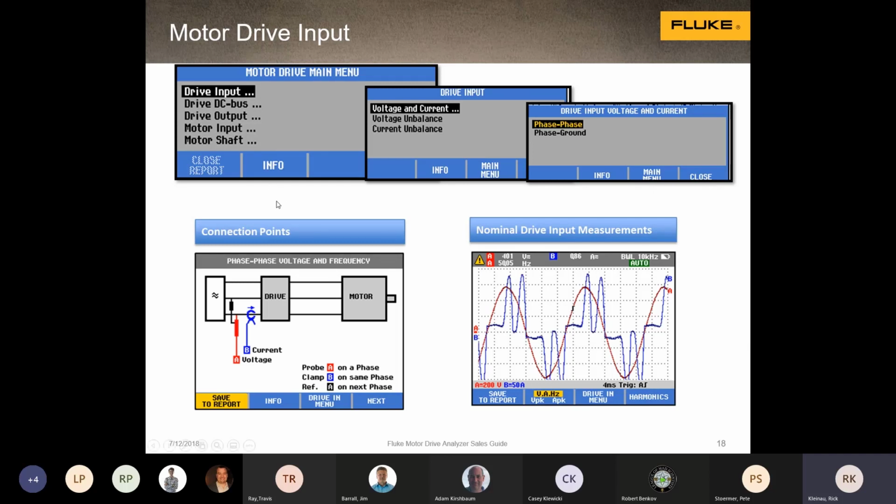So generally, we don't recommend the scope meters to troubleshoot, say, a power issue in the power network. And the PowerLoggers, we don't recommend for the output side of the drive because their measurement technique, which is governed by international standards, is set up for a 60 hertz fundamental frequency, or in Europe a 50 hertz fundamental frequency, or on ships maybe 400 hertz.